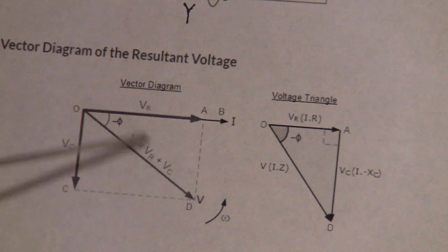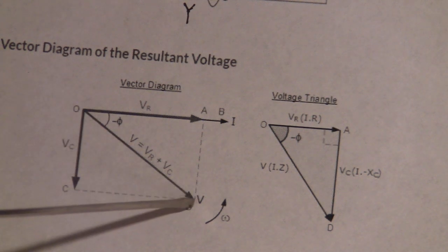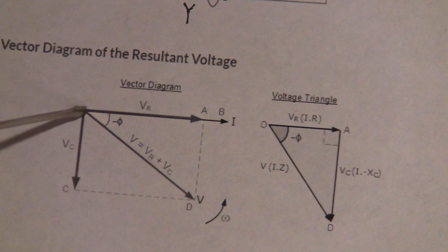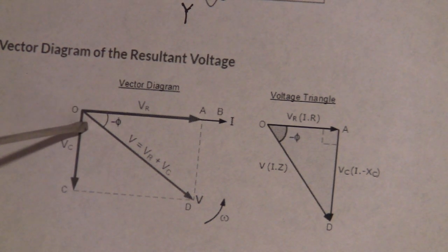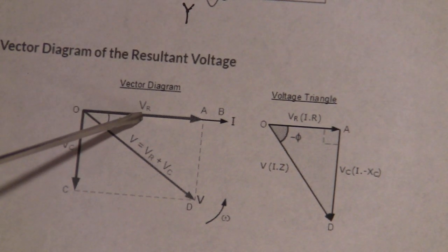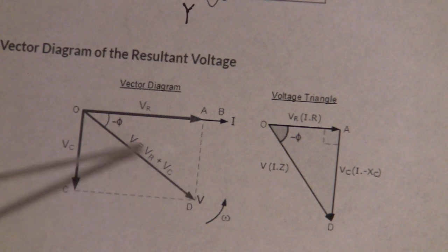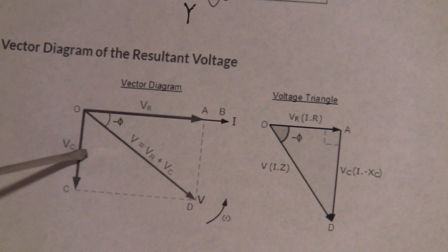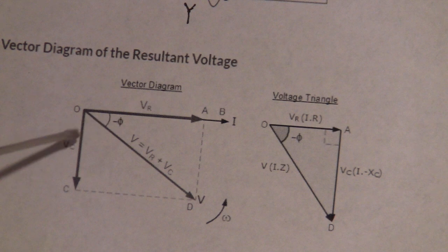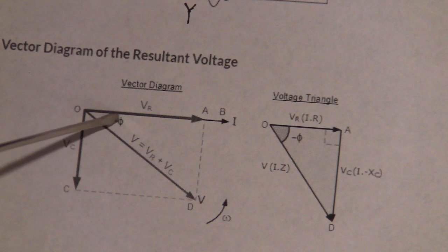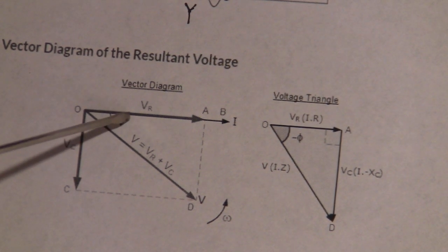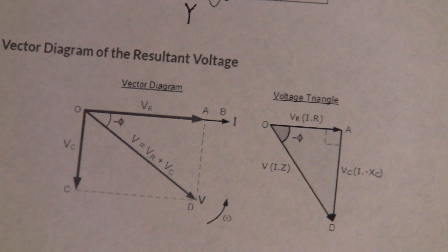So this is the yellow line. That is the yellow line, VC. It will be very, very close to the ideal, 90 degrees. But if this VR gets bigger, this will shift from 90 degrees up to here, right? Up to here. And there is an angle here. This angle is one of the parameters in the standard of the capacitor. Now we see what ESR is.